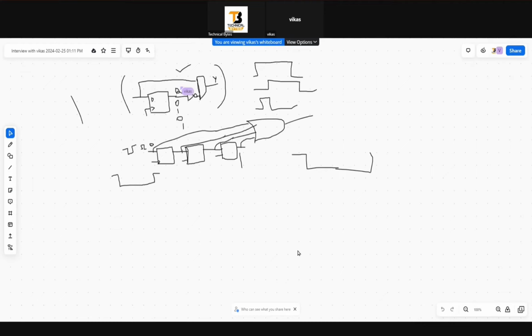One last thing. I have an input, maybe you can write it down. One input name is, let us say, valid signal. Another signal is data signal. You may have heard of the valid-data protocol. I have only valid and data, no ready. Data you can consider 8-bit or 24-bit, it's not a problem. The problem is, once my valid goes high, it always remains high. It is not going zero when data is not valid.